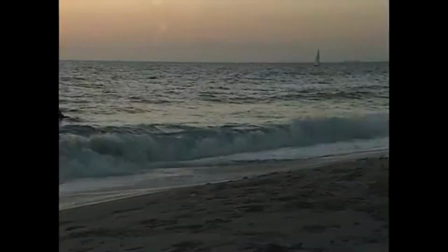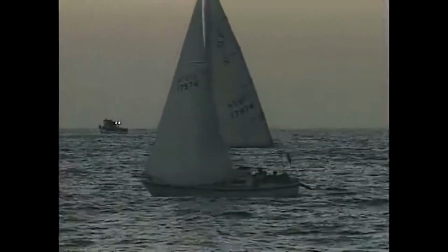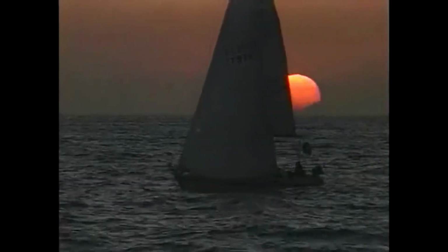Now consider a larger sail. A sail about 20 feet high and 10 feet across would create an area of over 14,000 square inches. The same moderate wind pushing across this larger area would produce over 1,400 pounds of force. This is more than enough force to move this sailboat, and it's more than enough to create a serious threat to safety if not properly controlled.